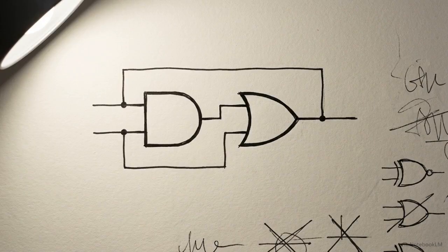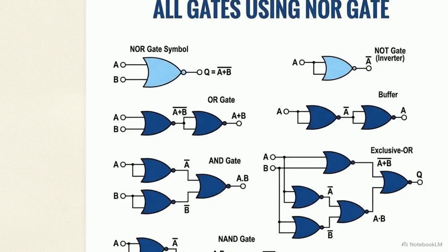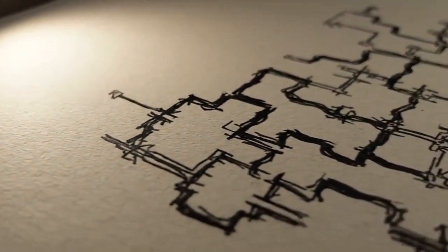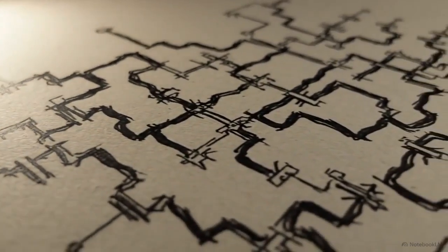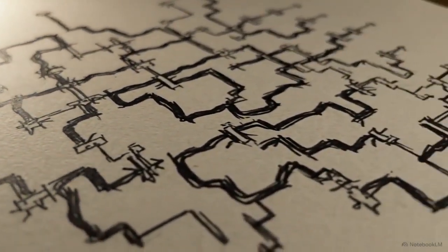To build a true OR gate, we must ignore that textbook error and derive the architecture correctly. It only takes 2 gates. Look at the correct 2-gate sequential layout here. We run a standard NOR operation on A and B, giving us an inverted OR. Then we pass that output directly through our newly built NOT inverter. The double negative flips it back to positive OR logic. Deriving functional completeness from first principles is necessary because it exposes the mechanical flaws that blind memorization hides.